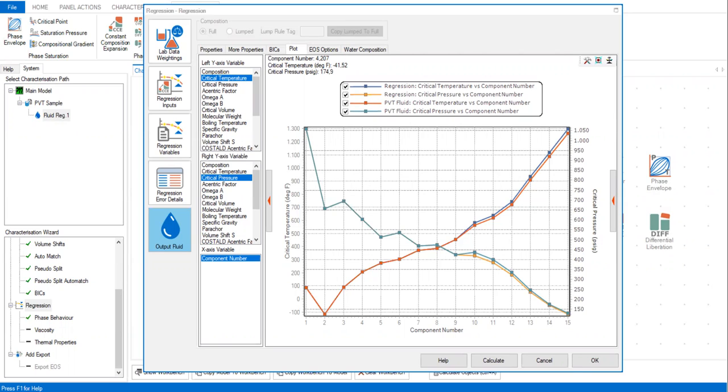All right. And as the error results of the primary regression run are satisfactory, we now need to validate the equation of state or the model against all available data to ensure that the model is representative of the fluid in the variety of scenarios. The procedure for the validation is to simulate the lab experiments in the same way as when we previously quality checked the model prior to the primary regression. So basically, we just open the result and let's see whether the matching is good, whether it is natural, and something like that.